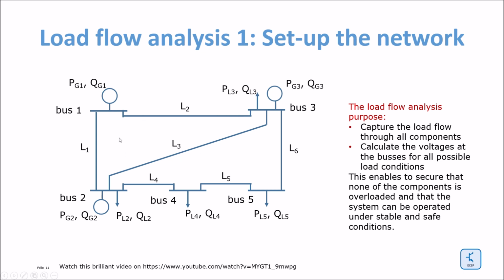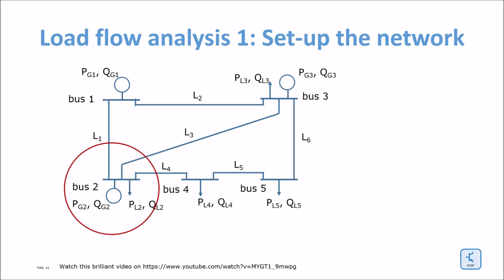And we want to calculate the voltages and the phase angle of these voltages at all the nodes, at all the buses, under all possible load conditions. This makes it possible to ensure that none of the components is overloaded, and the system can be operated securely and stably under all conditions. We want to have a closer look now at one of these buses.